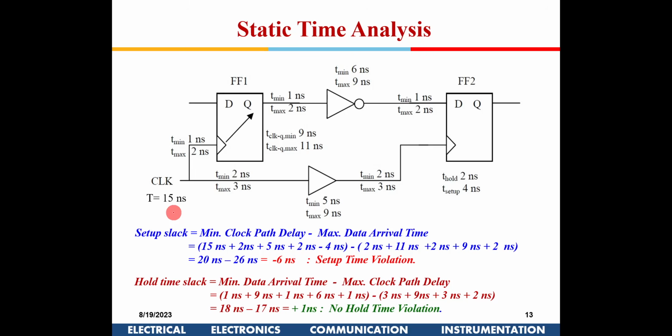What are the other options available? We can take a different inverter with less max delay. Yes, right. So another option is to reduce the delay in the data path. You can choose a flip flop which is faster. You can choose an inverter which is faster. That could be a slightly tricky issue, we may not have that. What could be an easier option?